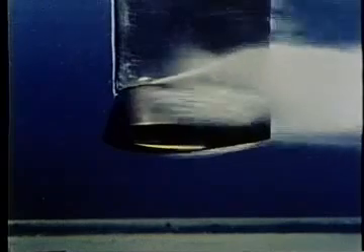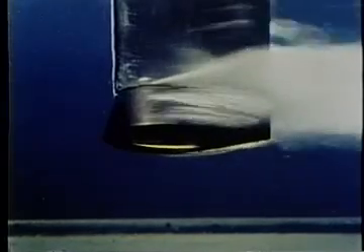At higher speed, and thus larger Reynolds number, the appearance of the cavitational flow changes. Transition from laminar to turbulent boundary layer has occurred. Laminar separation has been suppressed, and cavitation now begins near the minimum pressure point close to the leading edge.